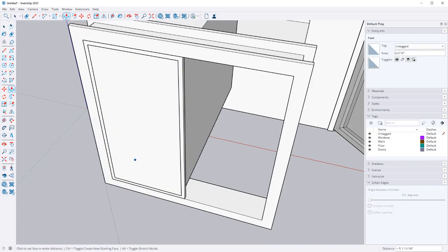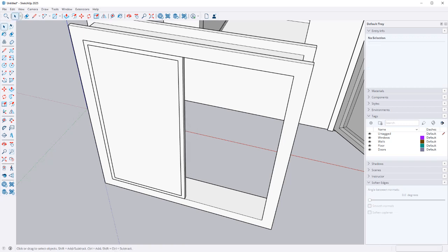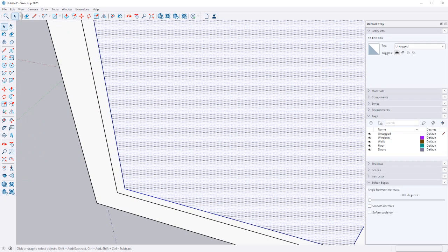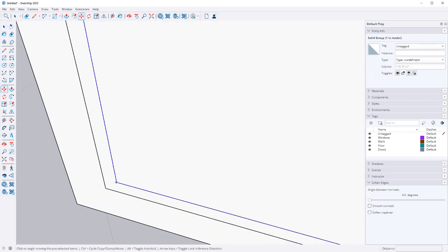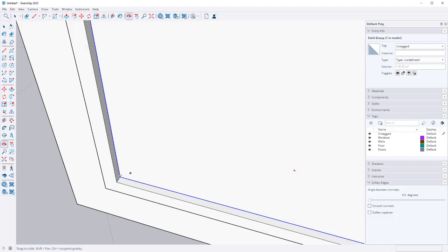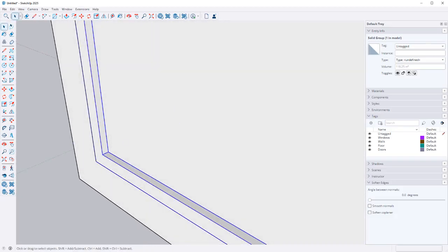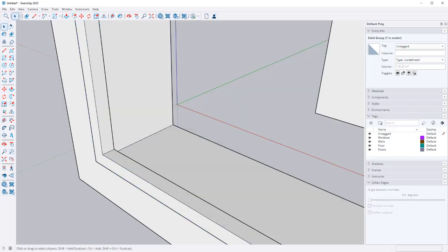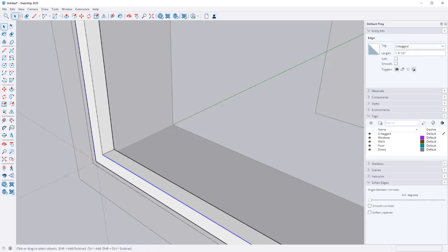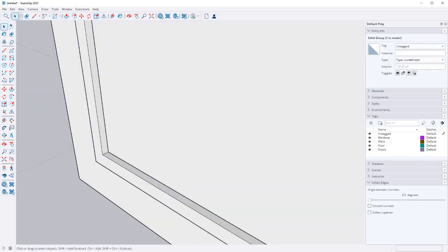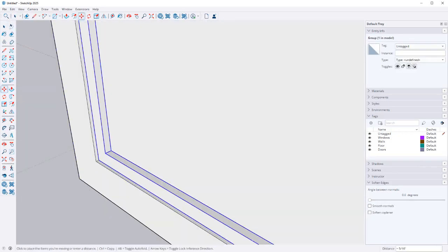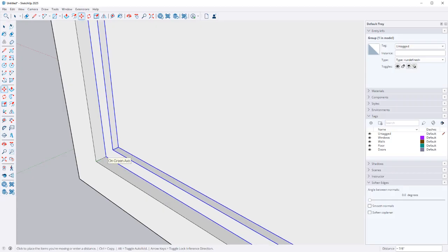And I tried, see, I'm moving this way. It's kind of hard to see sometimes. And I'm going to make it 0.125 or 1/8 of an inch thick. Triple click it, group it, and then I'm going to move it just inside of here. So you can see right there, the one I've got is this big one right here. These two are both going to move. Well, actually, let me cut this one out, go inside of this little mini frame, paste it in place, and then I'm going to shift this mini frame back a little bit.